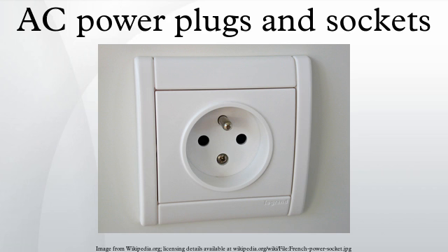It has earthing clips on both sides to connect with the CEE 7/4 socket and a female contact to accept the earthing pin of the CEE 7/5 socket. It is used in almost all European countries. Currently, appliances are sold with non-rewirable CEE 7/7 plugs attached. This means that the plugs are now identical between countries like France and Germany, but the sockets are different.